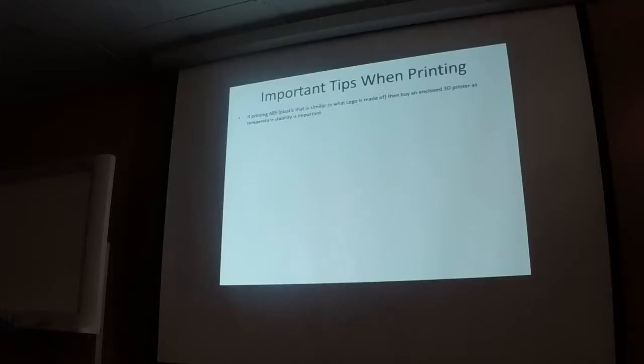So important tips when printing. If printing ABS, which is similar to Lego, then buy an enclosed 3D printer, as temperature stability is important, which I already mentioned. Leveling is very important. Leveling is very important. I can't mention that enough. There are new printers coming on the market that have self-levelers, but of course you have to pay extra premium for that.